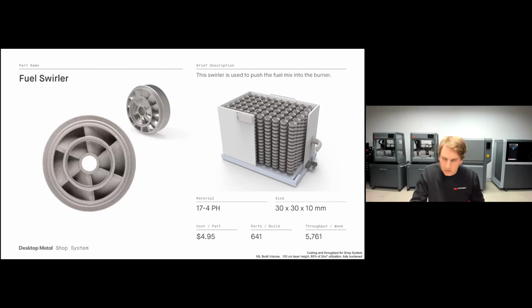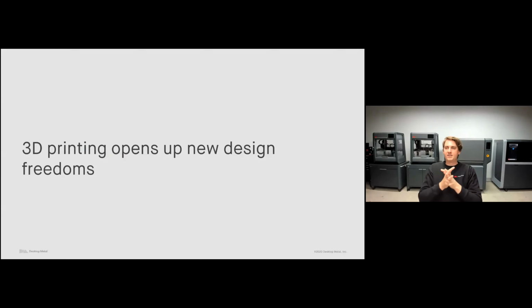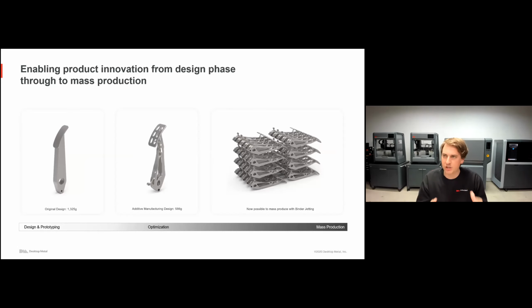Another thing that we're going to talk about is that 3D printing really opens up these new design freedoms. No longer are we really just so constrained to designing for our traditional manufacturing methods that are very restrictive, but now we can open up these new design features that are no longer just possible in low volume, but now with binder jetting, we can actually produce in high volume. On the left here, you can see, very basic design of a pedal, originally weighing about 1,300 grams.